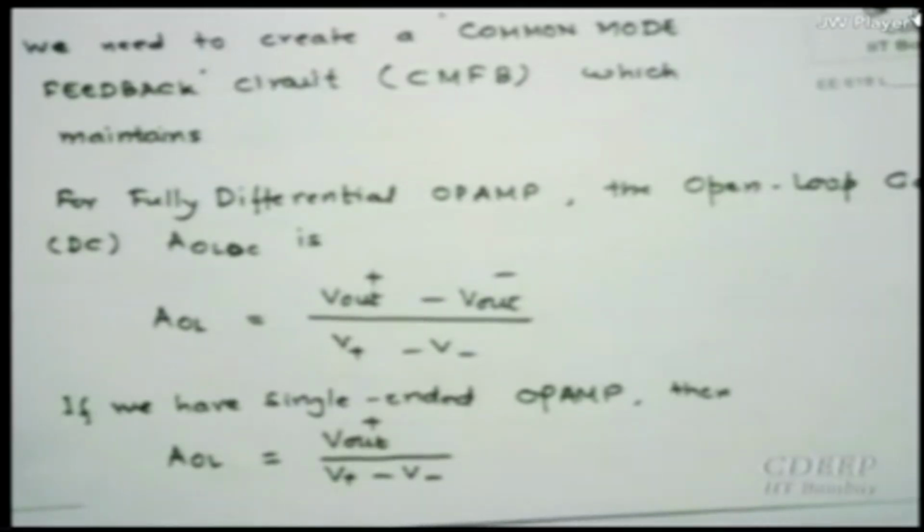But that doesn't occur; GM1 minus GM2 occurs, and how close they are decides your CMRR. Now the common mode voltage is not a constant quantity at all, as we will show you next time, and on different days it will show you different CMRR operation. We would like to hold that common mode voltage, and that is called a common mode feedback circuit.